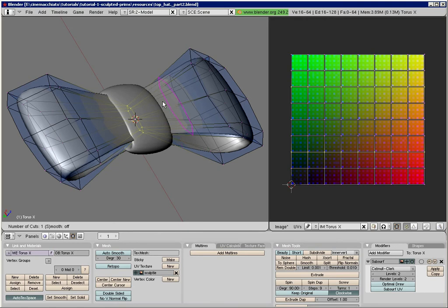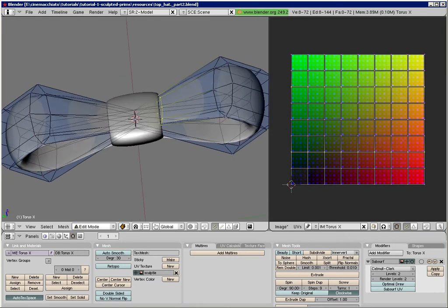Every time when you position the mouse near an edge, Blender will calculate a new loop, which passes through this edge, and cuts it into 2 pieces. Move along your object until you find a convenient loop. Then click the left mouse button. Now the new loop will be created. And again, by moving the mouse, you can move the loop around until it is located exactly where you want to place it. Then left-click, and your new loop is added to the mesh.